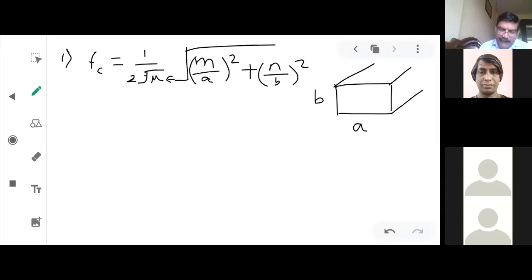The earlier lecture also, if you remember, it was width of the strip, then width of the ground plane, then dielectric material. So the length part talks about the phase shift when a wave propagates from one end to the other end through a transmission line. At that time, the length matters. Otherwise, it is the cross-sectional dimension and the material used. So here you can see that the cutoff frequency depends on the cross-sectional dimension and mode.